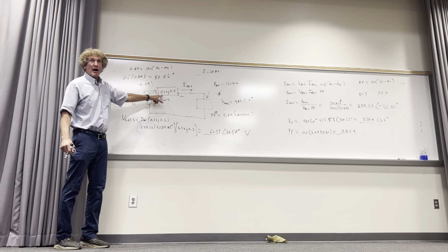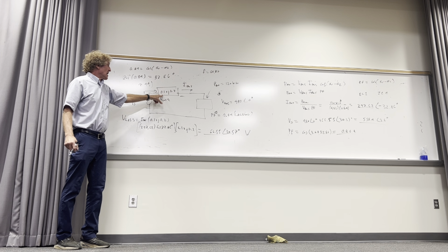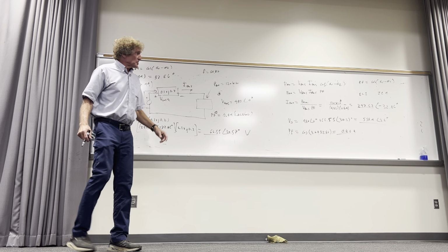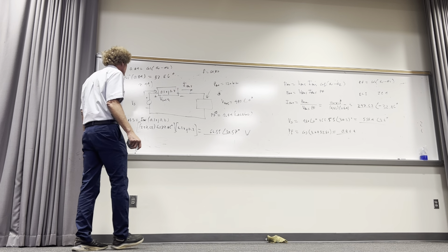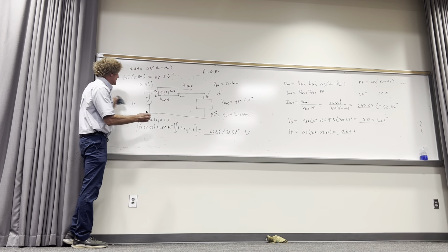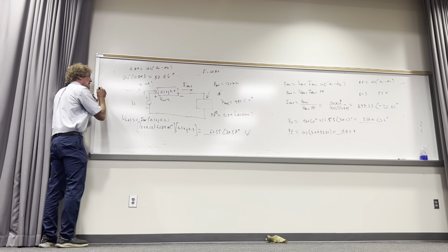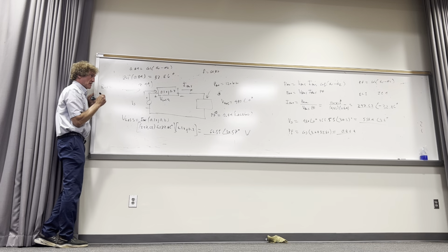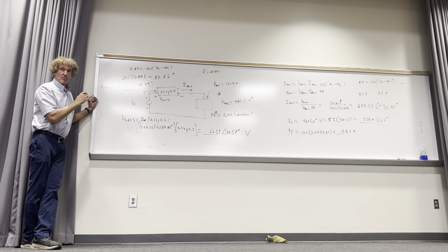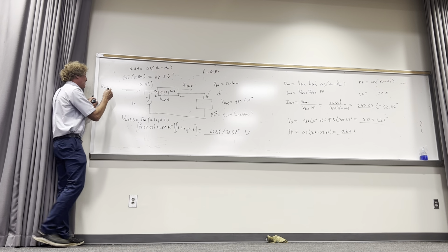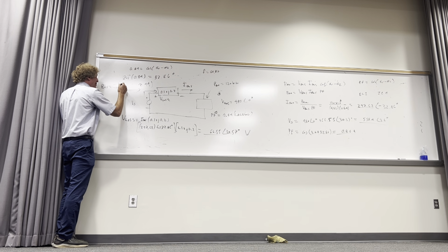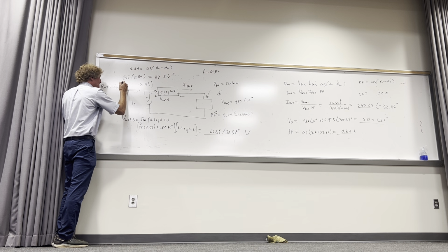How much power is dissipated there? Just take IRMS magnitude squared, so what is that? 297.62 squared, and then multiply it by 0.1. I asked this question, so how much is dissipated, and I'll call it P loss. Does everybody follow me what I'm doing here? It's just IRMS squared times, and this would be called R line, I think, in the book, but it's really the losses of the line. So what do we get for this?